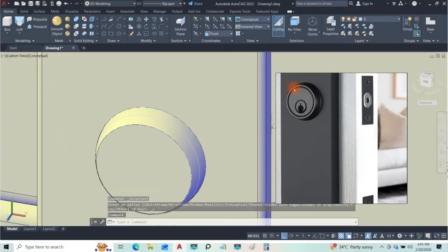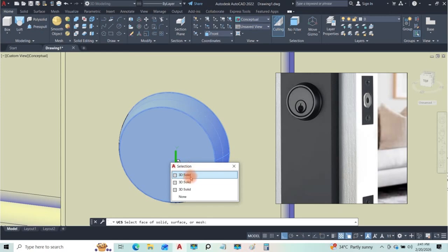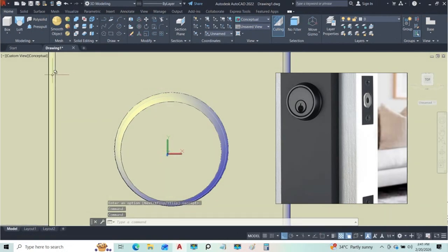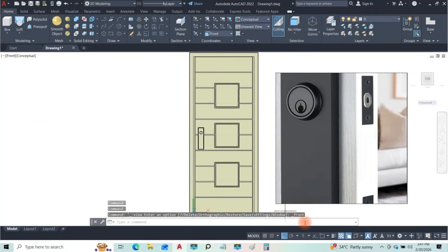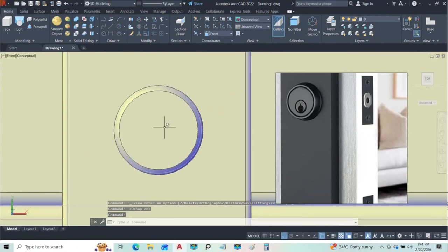So this one, I want to have this cutout opening. So again, I have to set my face working plane to this, press enter, and then I can create my circle as well. Turn on my snap mode, object snap mode, and I can also create another circle.